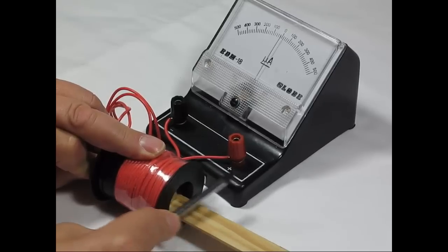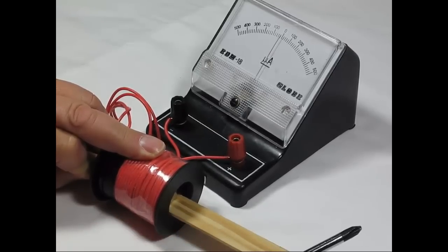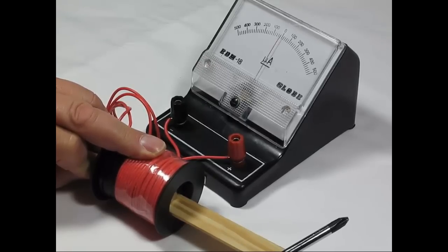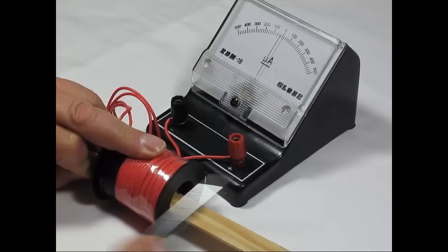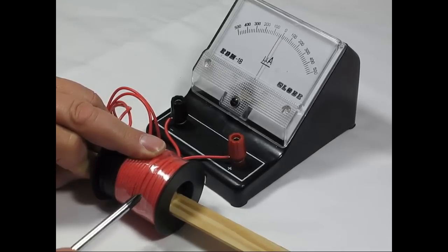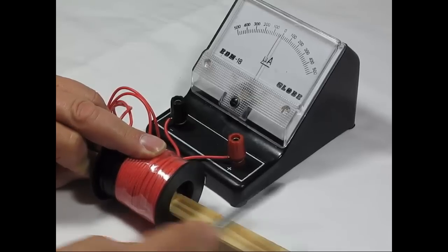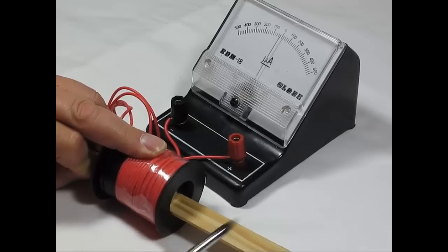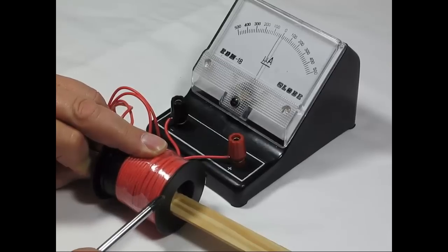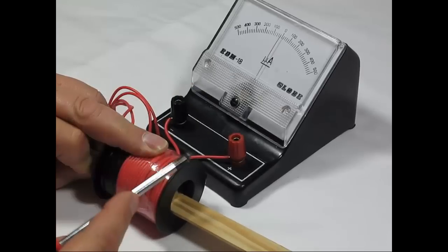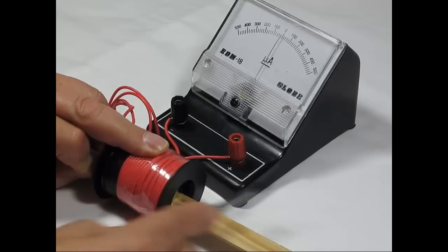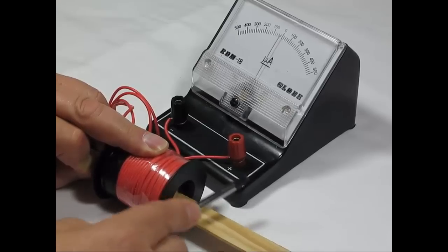That causes the magnetic field to move. So this is how a proximity sensor works. A proximity sensor actually has an electromagnet, not a permanent magnet, and it has a coil of conductor. And this is stationary, and when a metal object moves by, see the needle moving? When an object moves by, it disturbs the magnetic field, and the current flowing in the sensor amplifier, which would be this device now, senses that change in the magnetic field and says, aha, there's an object there.